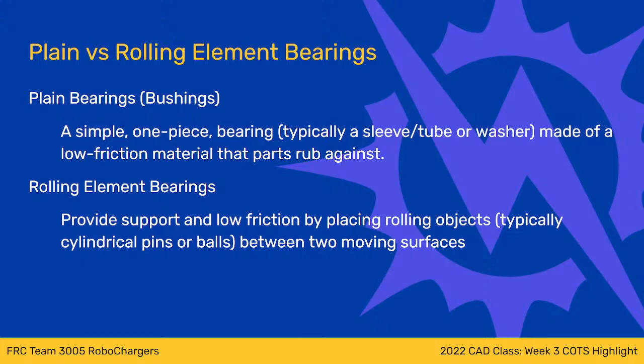Plain bearings can be made of a huge variety of materials. They're typically metal that is particularly slippery, or plastic that's very slippery. In some very intricate mechanisms, like expensive watches, they actually use jewels like rubies, or I think amethyst might be one they use a lot. Sometimes they're lab grown, sometimes they're genuine, and they use those because they're so hard that they don't wear out. So there are all kinds of materials you can make plain bearings out of.